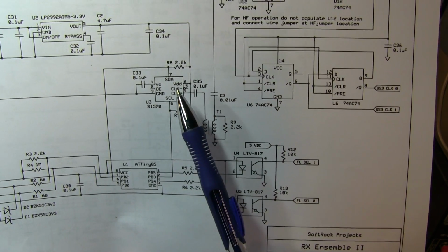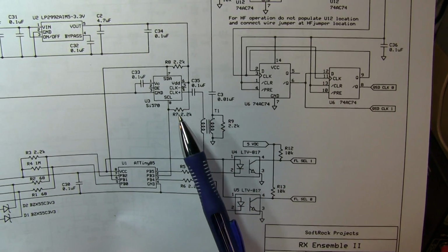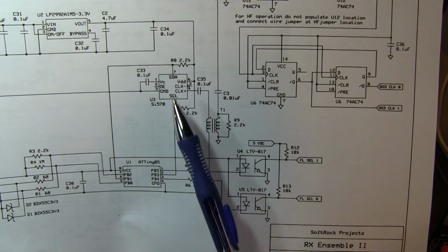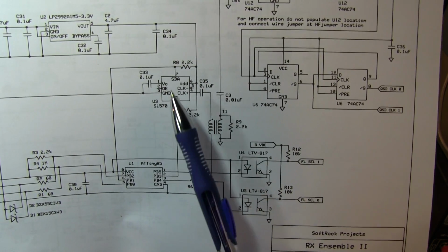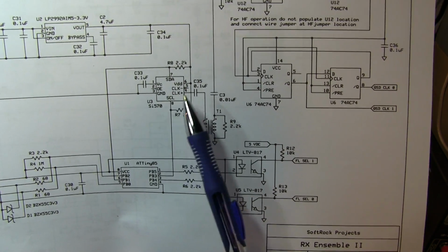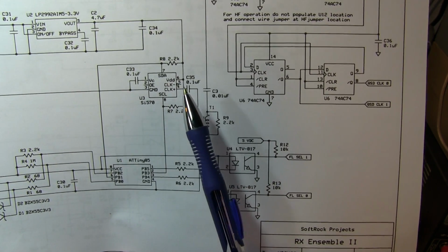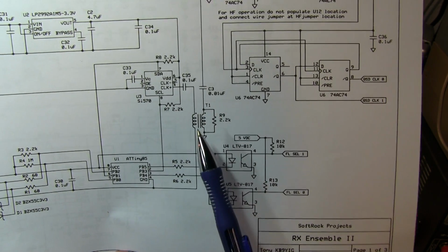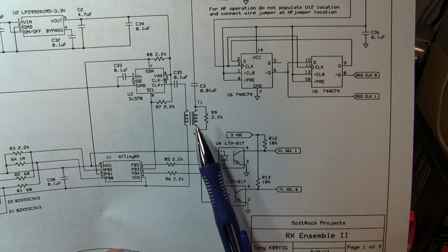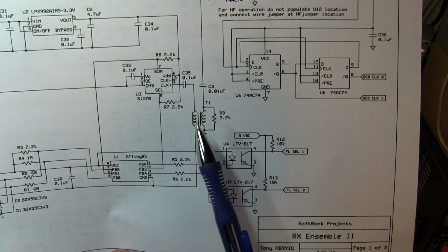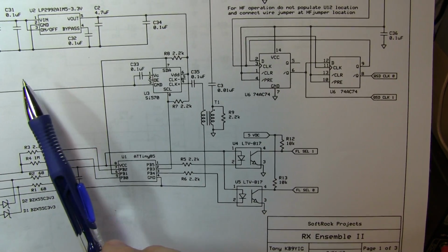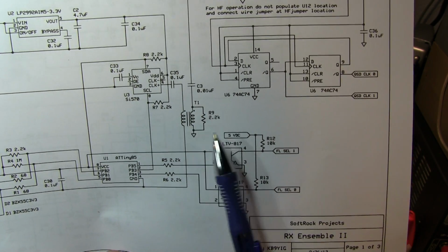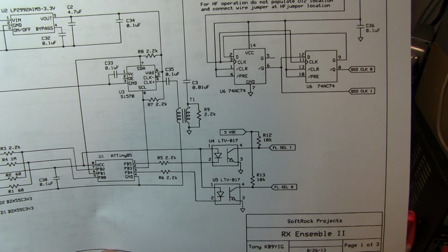He's the programmable clock oscillator, and he's programmed through an I2C bus, and those are the two pins here. So it gets commands through that bus to tell this device what frequency to create, and its output comes out through this capacitor in through this transformer. So we cross that galvanic boundary there, and that's how we get from essentially our digital power supply domain to our analog power domain on the other side of this transformer and these optocouplers.